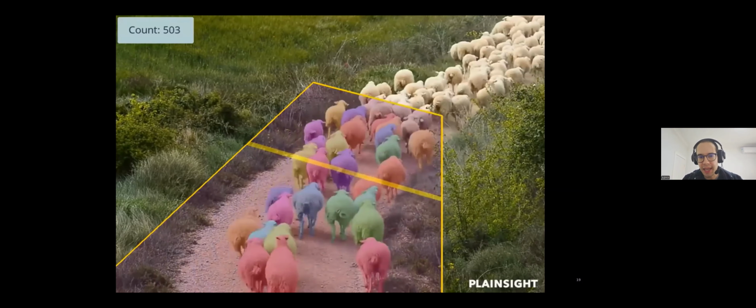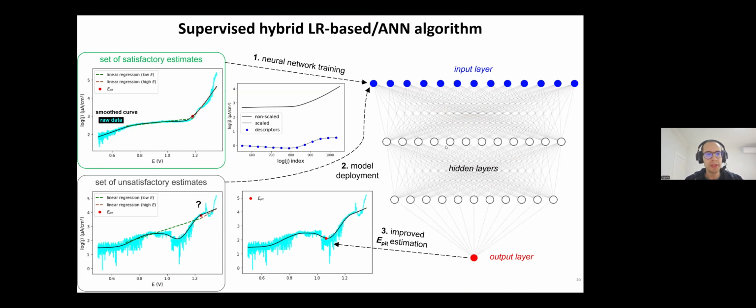We did exactly the same in these polarization curves. It seems complex, but this is one example of a polarization curve. We manually labeled the pitting potential, which is here, okay? So we verified that based on domain knowledge. I assessed, out of thousands of curves, that these were good estimations, I would say. In fact, we used a linear regression method for getting these labels. And it solved our problem with linear regression, I would say 80% of the time.